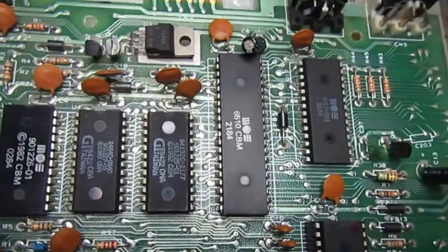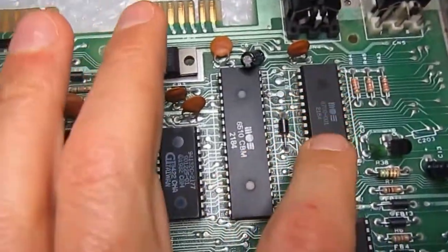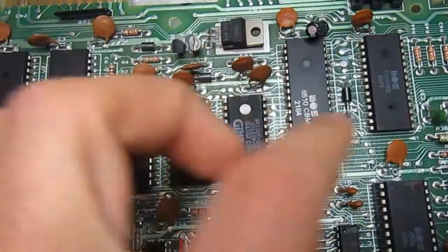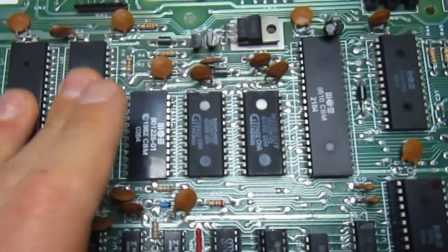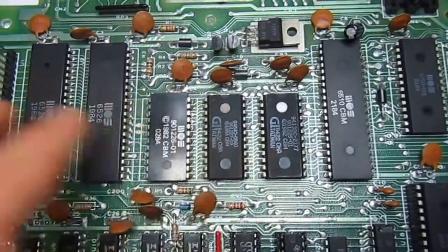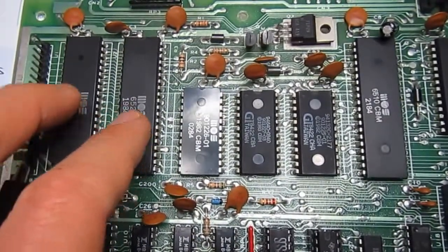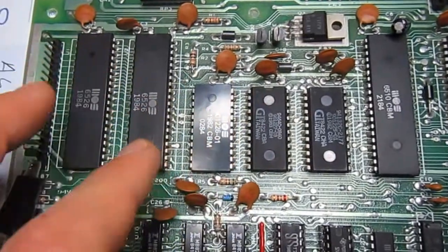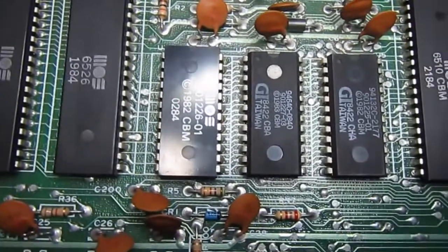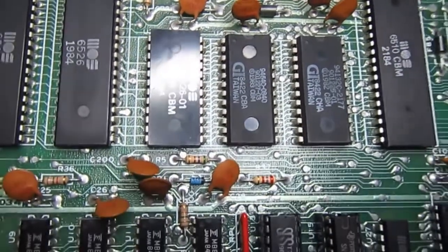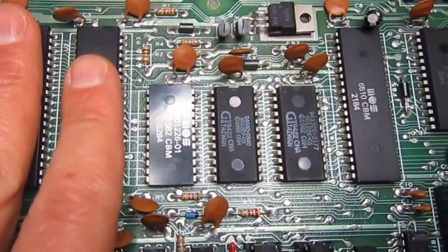Probably also the PLA, but that was not affected by this problem because the PLA only works with the addresses, not the data bus. Data bus was the problem when you select more than one chip at a time. The data bus is driven by all the selected chips, so they conflict on the data lines. So probably it is one of the ROMs, or these two.